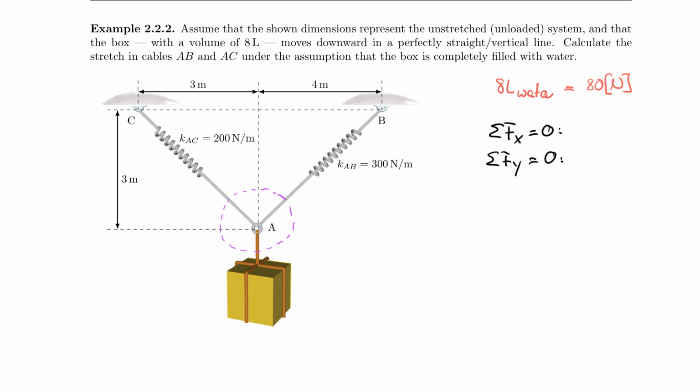In other words, if there was another spring or another cable, let's say I have another spring here, then this would not work because I also cut the spring here and I would end up with 1, 2, 3 unknowns, and therefore my two conditions would not be enough anymore. And you could say, what is with the sum of the forces in the z direction? Then I have a third condition.